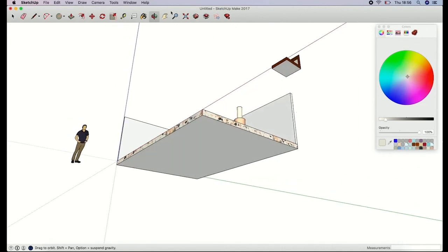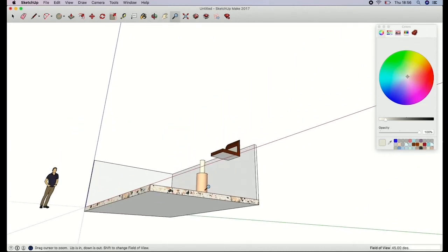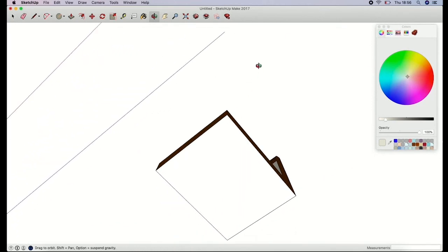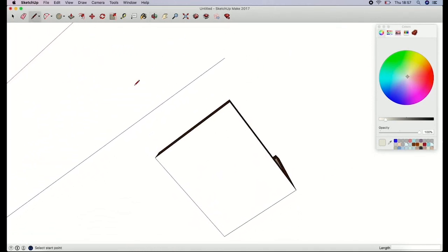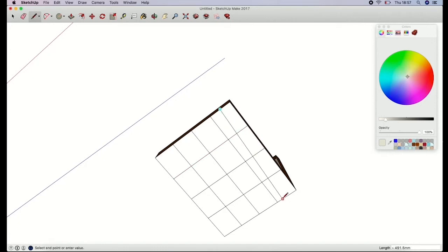And to put some legs on it, I move the diagram here and zoom in, and then rotate this round. If you hover around different points, it will snap to the midpoint, which is quite useful. So sometimes I make grids on different objects to find center points. And if I do that enough, hopefully I'll get to the 4 corner parts of the chair. So these parts essentially.